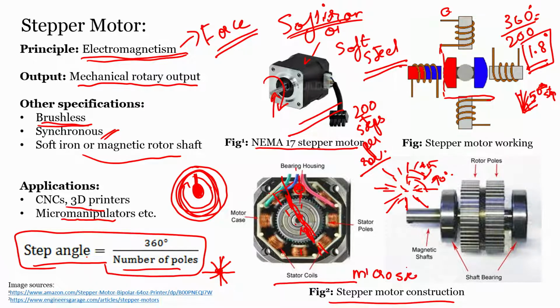For this, we do the process by using an external electronic circuit or something like a motor driver, which will help us do micro stepping. Okay, micro stepping is nothing but using the same stepper motors, by exciting two coils at once, we are able to get micro steps. Cool. Okay, now we will see the working of the stepper motor.